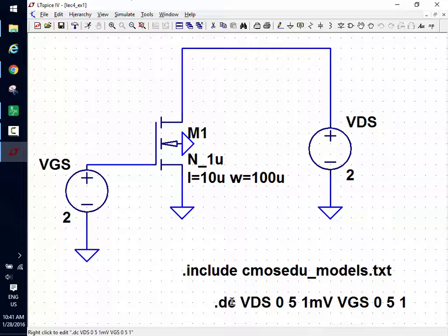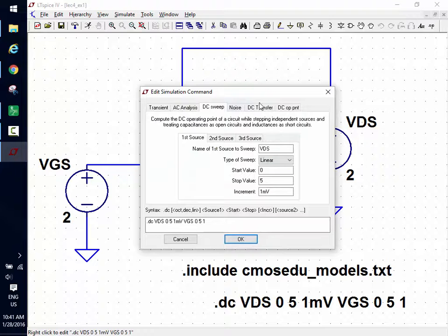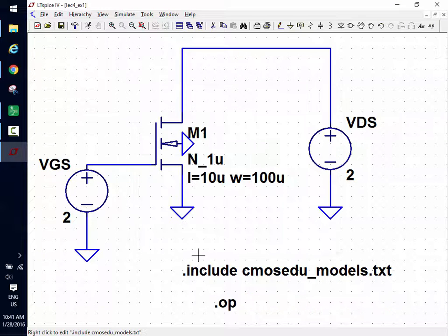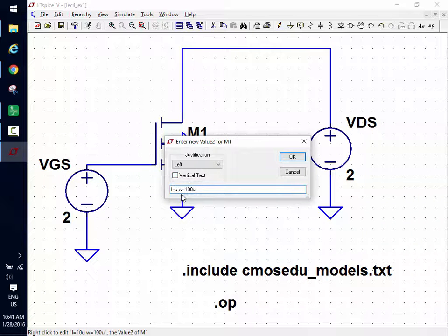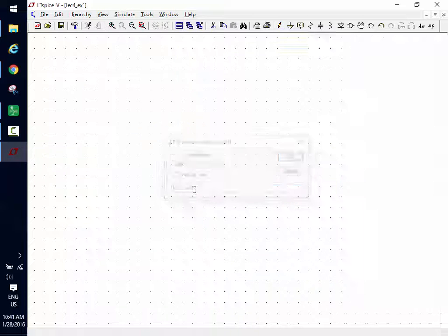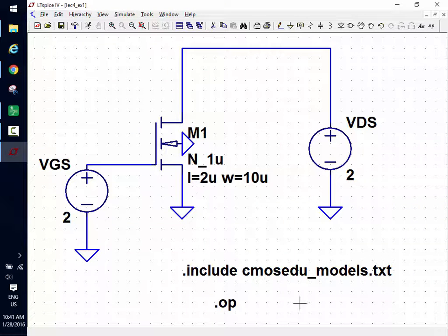I just want to show, I'm doing my homework here, that I calculated the DC correct. Tell me what's the best sim to do that. Yeah, let's just do a .op. All right. I could do a .tran too. Let's do both. Let's live it up. Okay, so let's go to .op. Boom. Then let's change the size of the devices to 2 and 10. And let me just pause for a moment. Got my include so it doesn't use the wrong models and give me the wrong results. I got to do one other thing.